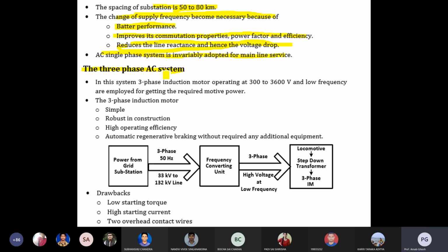So that's why it's quite a problem dealing with the three phase AC system for traction purposes, for directly collecting the power. Otherwise, the output voltage from the three phase is definitely more than the single phase voltage. Everything would be beneficial using three phase, but the problem is unbalancing, which has a severe effect. That's why we are not using the three phase system for traction purposes.